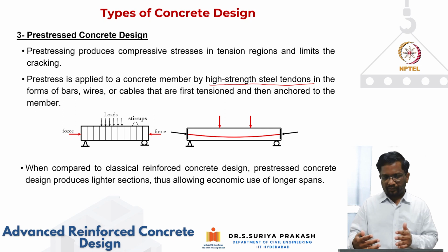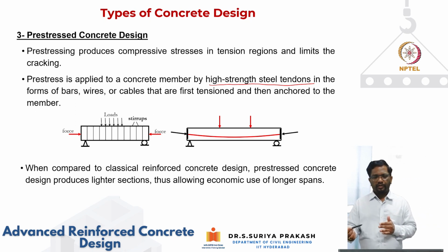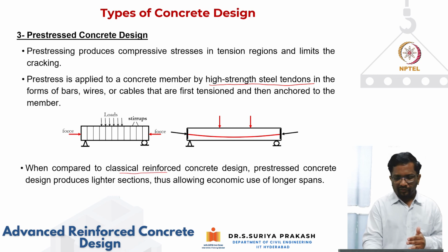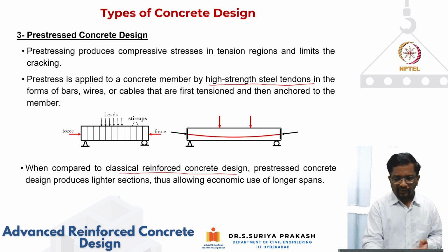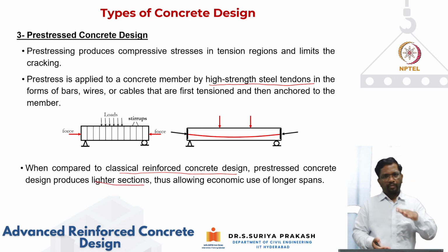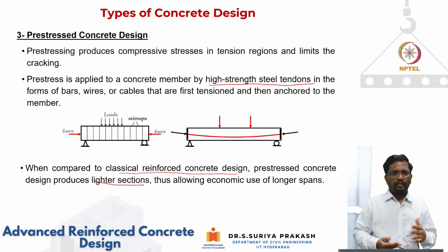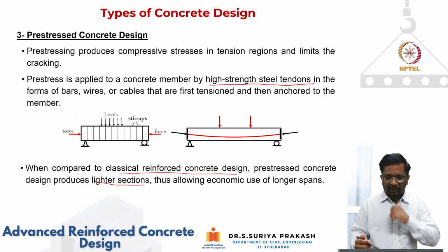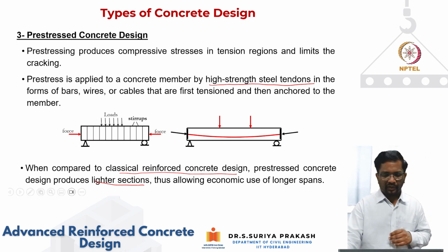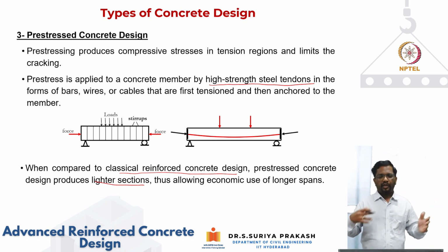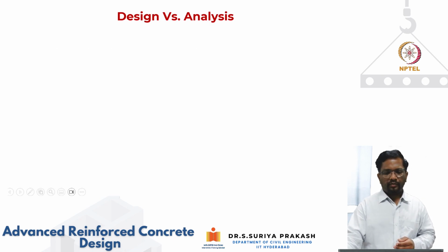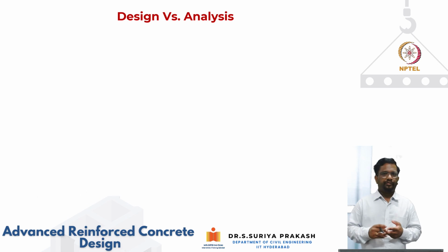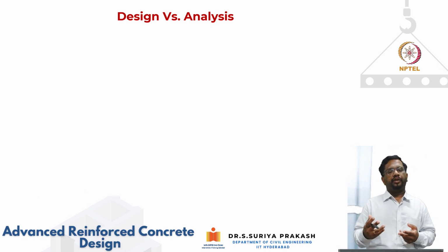because of external loads. So what are the advantages? When compared to classical reinforced concrete design, pre-stressed concrete design usually produces lighter sections. That means the sectional depth requirement for particular service loads or design loads is going to be very light, and it is going to allow economic use of longer spans. So usually if you want to have a longer span, we end up going for pre-stressed concrete design.